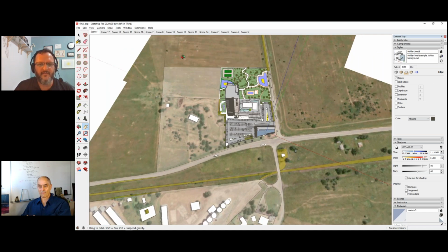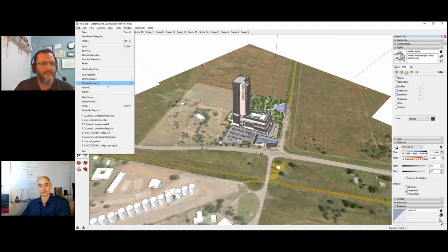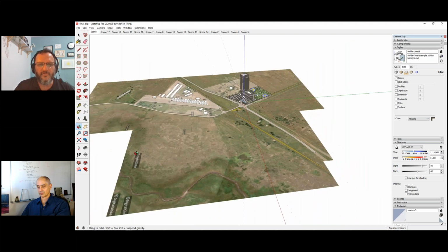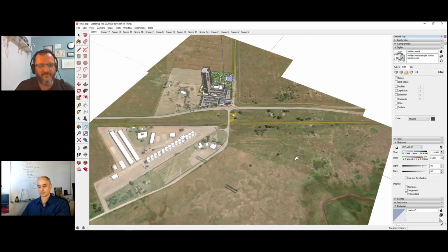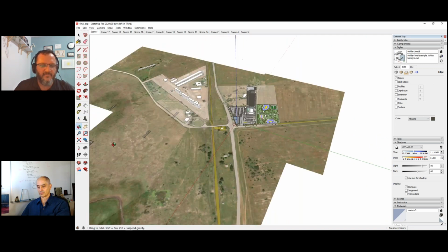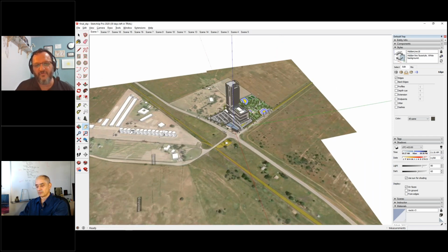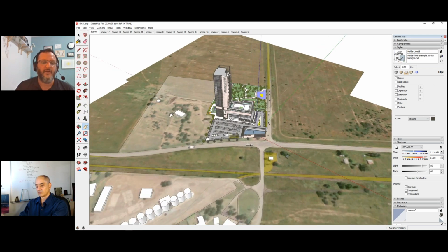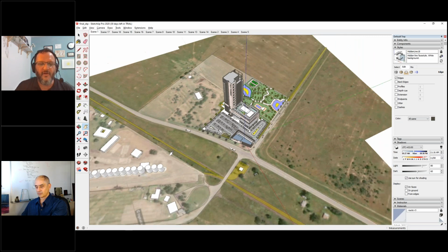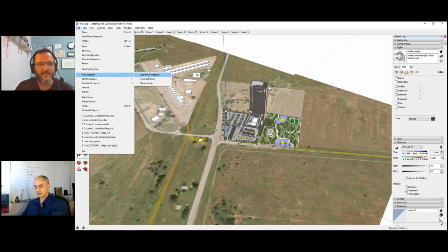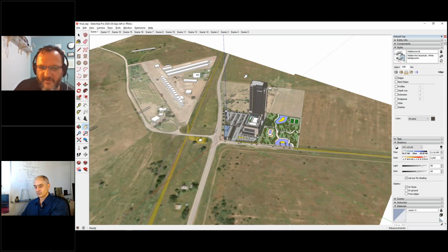Or the next, absolutely. Just one last thing I wanted to say, in SketchUp here we have something called geolocation, and you can add through Digital Globe any geolocation on the planet. It will import the surface for you of that region. This is a region in Southern Africa, so I imported it, and it's not as precise as a land surveyor's drawings. However, it gives you instant, rough GIS and visual of that area. So you can start accurately before a surveyor has gone out to your site to gather that type of information, instantly through using this function called add more imagery in the geolocation function in SketchUp, which is a very, very powerful feature for any design architect.